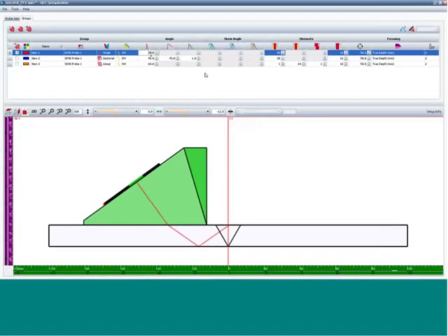Okay, this one A-scan starts on element number 30 right here, element 30, and uses 16 total elements. So 16 elements times the pitch of each element, 0.6, equals 9.6 millimeters. So my aperture here is of basically a 10 millimeter probe.